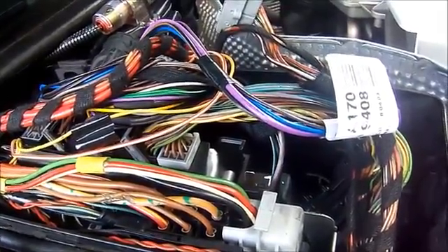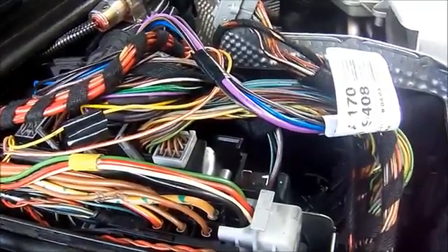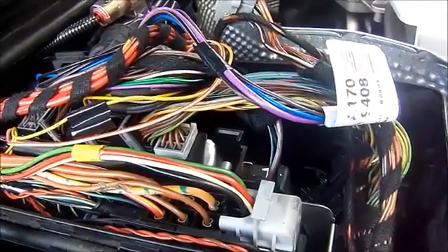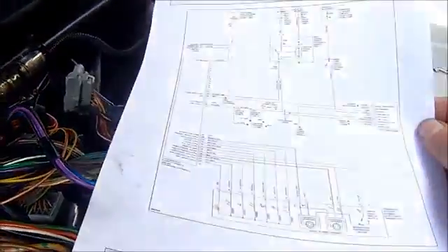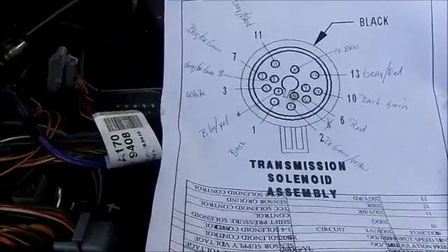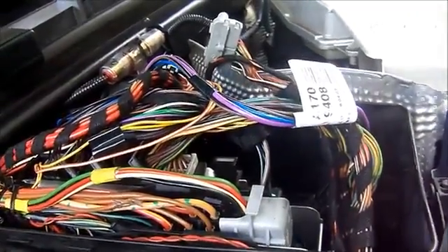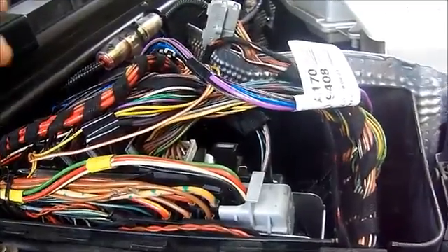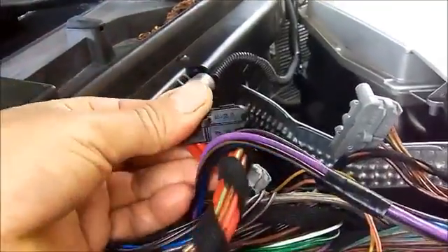I disconnected the TCM, or the transmission control module, and scanned it again, and we still have that P0753 shift solenoid A electrical. I got my wire diagram here, and I already checked, made sure that the connector was assembled properly and all the wires are where they're supposed to go. What I did notice on the TCM connector was transmission fluid in it, and when that connector leaks, it goes through the wiring, and as you see here, there's transmission fluid in this connector.